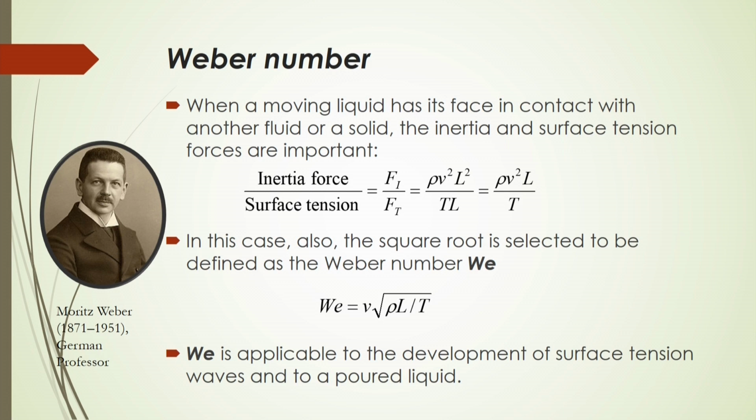So, to get the stabilized form of these droplets or particles in a medium, you have to consider these two forces, and based on these two forces the Weber number is defined. There will be a certain value of critical Weber number, based on which you can say whether this bubble or droplet flow will be stabilized or not, whether the size will be stabilized or not, and whether it should be spherical or not.